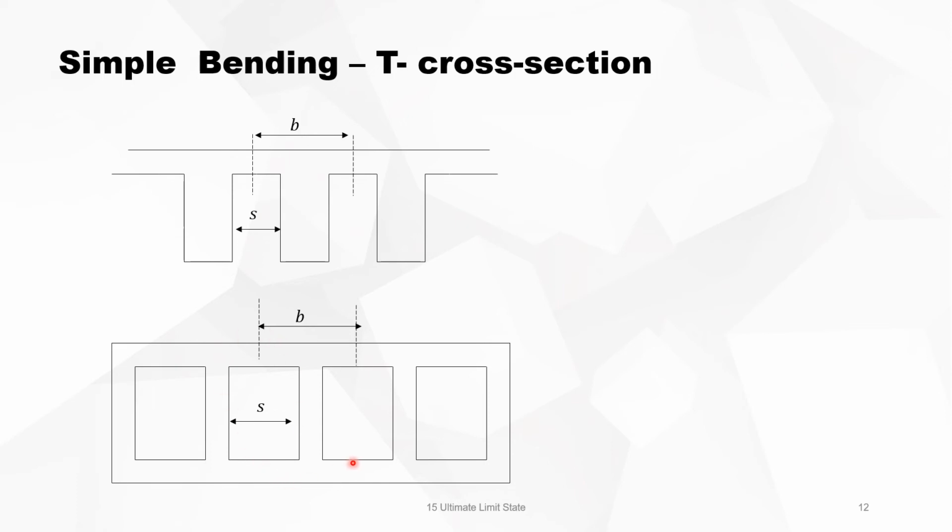Now, if you make a design, then you want to make it easy for yourself, and it is easy for the stresses and the strains. So you want that the width B should always be smaller or equal to the effective width. Why? Otherwise, you will have some strange effects around this point. So it's easy for you, then you can calculate it as a T section, it's no problem at all. So you try to take the real width B smaller than the effective width.